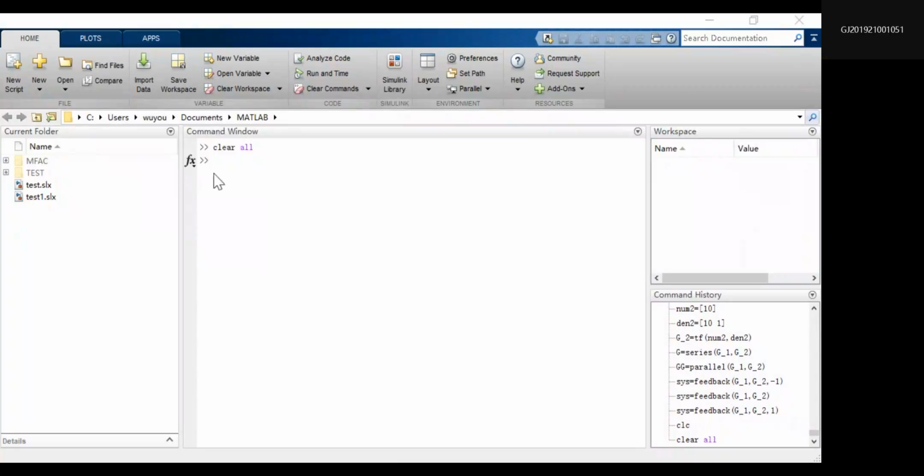So which menu should you refer to? Math operations, yes, math operations here. And see, we have Add here. First, we drag the Add block into here. And next we see a Sum here. Drag it in. Though the shapes are different, the functions are the same. You can choose whatever you like, okay? Here, maybe I use the circle one. And connect them. Just drag from one to another and a line shows up.